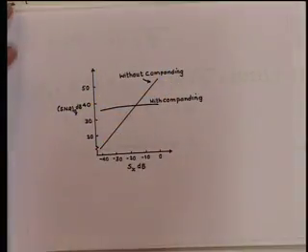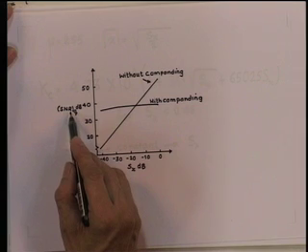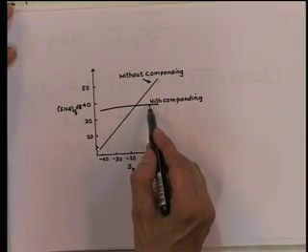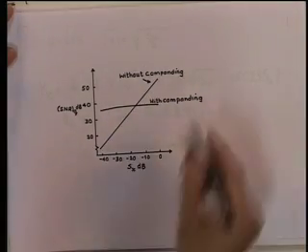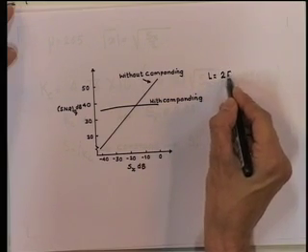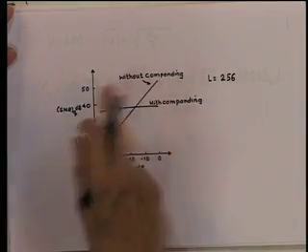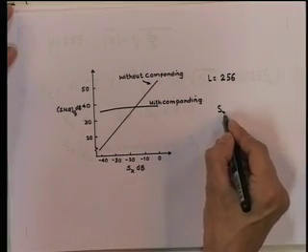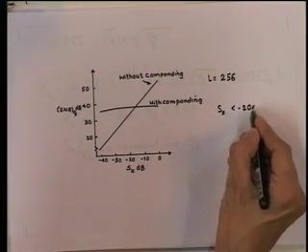Now, the figure here brings out this desirable feature by plotting signal to quantization noise ratio in dB versus input variance in dB with and without the companding when L is equal to 256. From this figure, it is clear that there is a considerable companding improvement for S x less than minus 20 dB. So, in the design of a quantizer, there are three important issues.